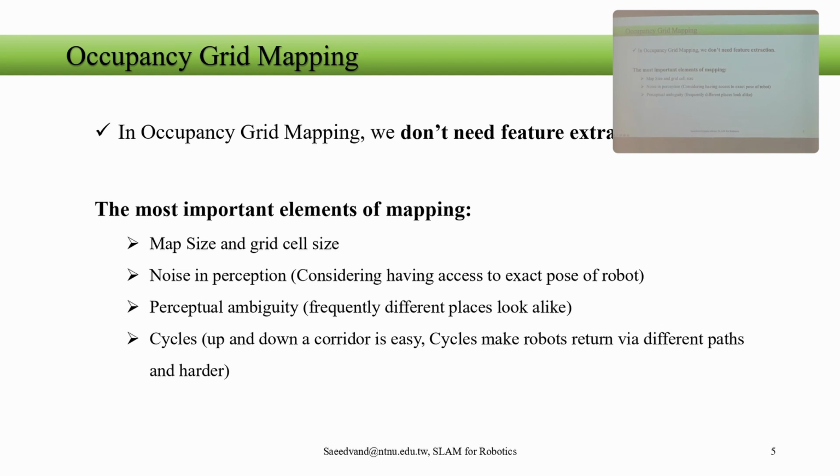Say you have, for example, this environment, and the robot is somewhere. Everywhere looks identical. There is no feature. So this is called the well-known ambiguity of the environment. Then we need to rely on control commands, motion commands mostly, or odometry mostly, in order to be able to construct the map. And of course, we have more error, and there are more challenges there.